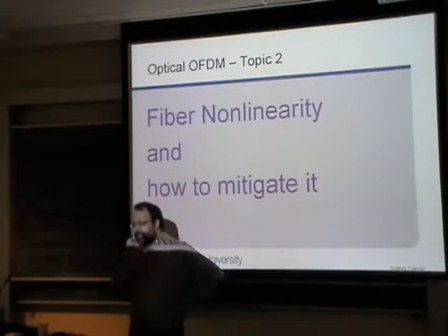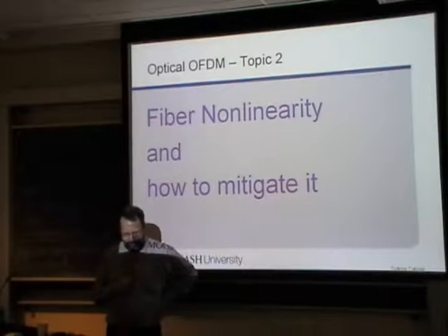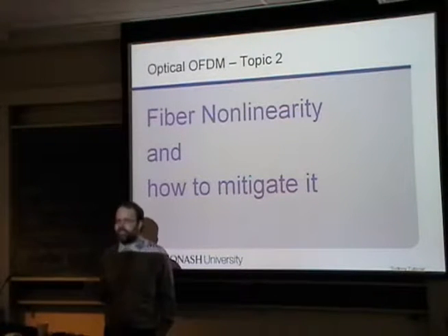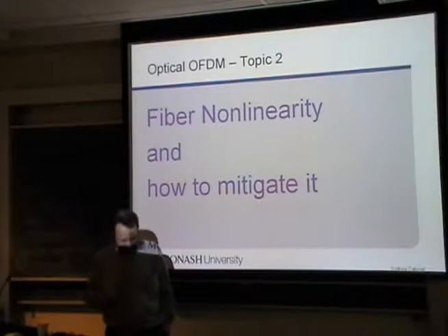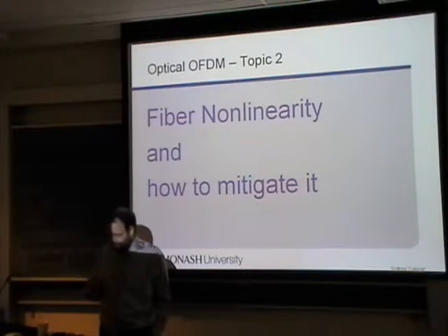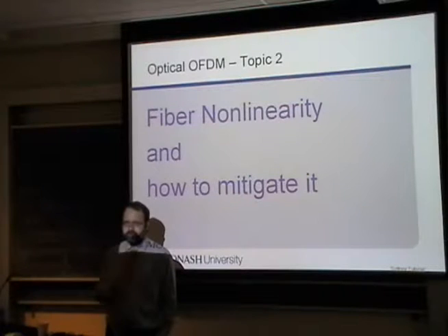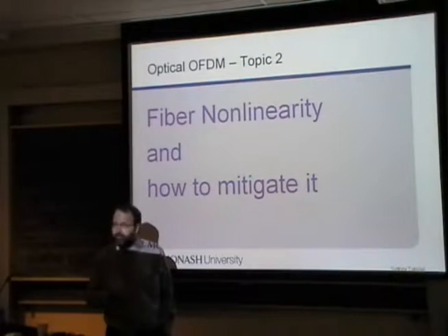This one is about how to use a bit of electro-optics and a bit of cheap electronics to mitigate nonlinearity. And the important thing here is I can mitigate cross-phase modulation, which everybody calls the nonlinear Shannon limit. So we've overcome the nonlinear Shannon limit, which means we can increase the spectral efficiency or the communications capacity of an optical fiber using only cheap techniques.